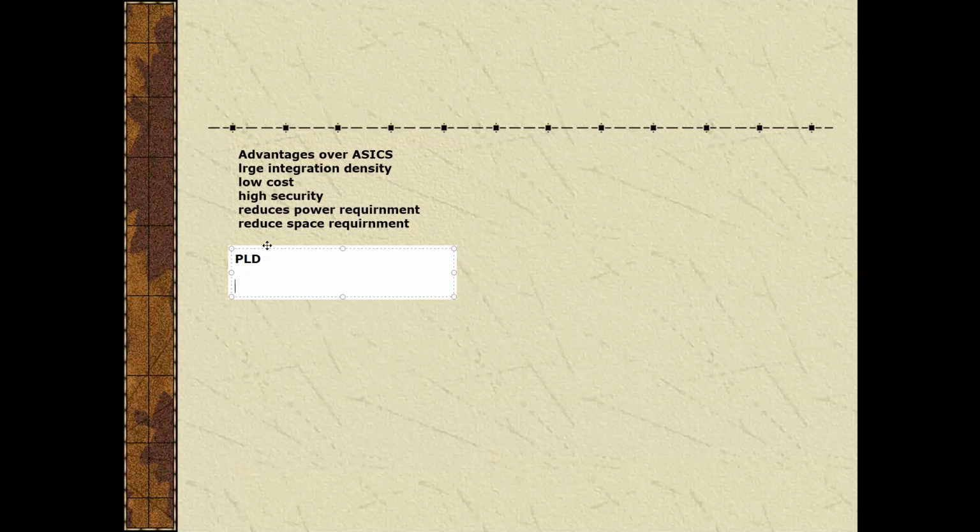Of all the programmable logic devices listed in the above section, the first programmable logic device developed is the programmable read-only memory. In programmable read-only memory, the inputs provided to the digital circuit work as the address lines and the outputs of the digital circuit work as the data lines, and PROM is an inefficient programmable logic device for logic circuits. The first device developed for implementing logic circuits is the field programmable logic array, simply called a PLA. A PLA consists of two levels of logic gates, a programmable AND plane followed by a programmable OR plane.